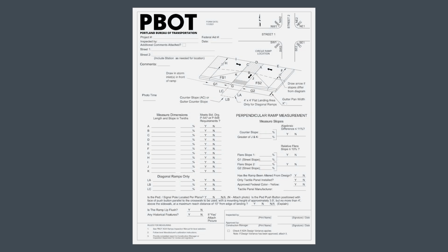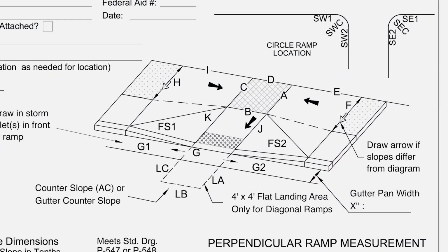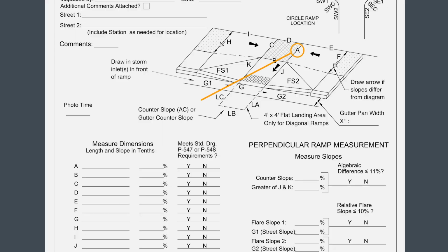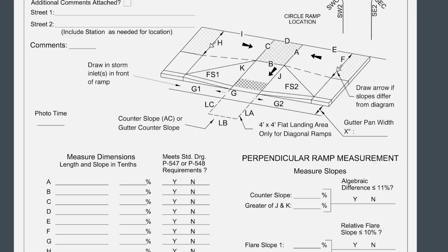To confirm that, you'll need to take measurements along the 4 sides of the panel: A, B, C, and D. On our form, you can see that the A measurement goes here, and so on. But hold on, if the panel is 48 inches and the level we require you to use is only 24 inches, where do you take your measurement?